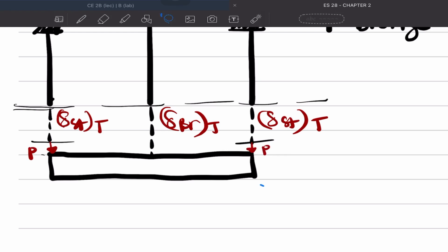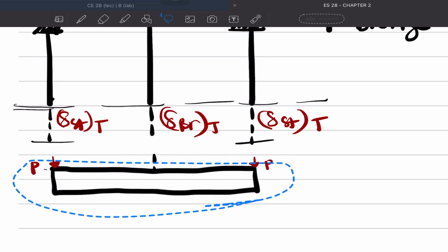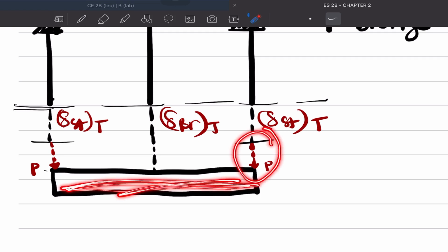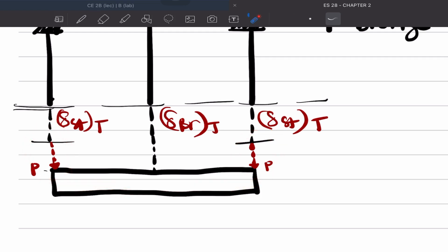This one is drawn a bit longer, and a little farther away, to make our drawing more exaggerated. So, in this case, there is no stress exerted by the bronze; the only ones carrying the rigid block are the two steel rods. They are the only ones exerting force. Okay, so this is the deformation of the steel rod due to the load that is applied, same as with this one, due to the load.